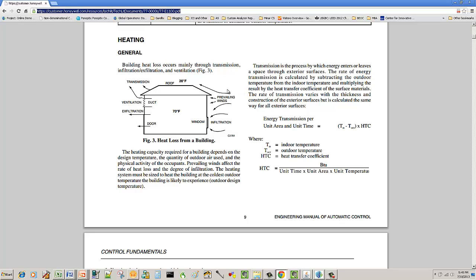If it's 100 degrees or if it's 20 degrees outside, we want to keep what's called our envelope. That's the exterior of the building. We want to keep our envelope positive. We want to keep our pressure positive, so effectively we're creating a bubble and we're keeping pollutants, allergens, things of that nature from entering the building, but we're also keeping thermal gain or thermal loss from the building.